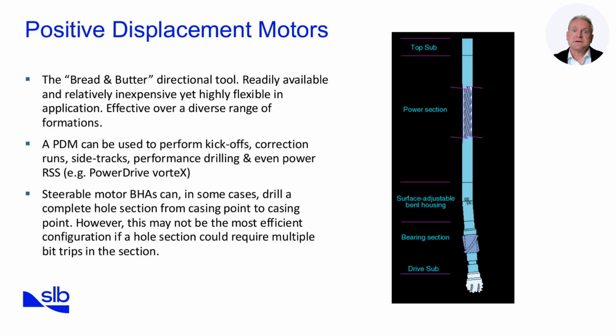A positive displacement motor is a type of downhole motor that converts hydraulic energy, specifically the flow of drilling mud, into mechanical energy to rotate the drill bit. It does this independently of the drill string rotation from the surface. In simple terms, mud goes in and bit rotation comes out.